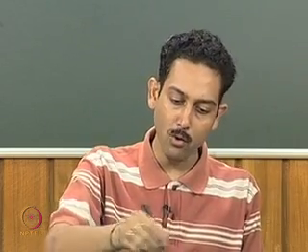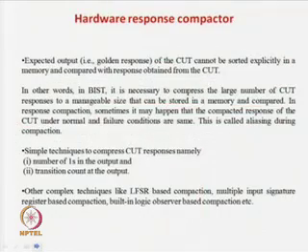So that is why we go for LFSRs. We can design the LFSR with the desired primitive polynomial, the desired characteristic polynomial, and if you want an exhaustive set, you have to go for a primitive polynomial; a list can be found in this paper. And if you do not require that, you can design another kind of characteristic polynomial, so that you may not have the exhaustive set of patterns, but you will have the required set of patterns. Again, if you want to select the sequence of patterns in such a way that your required test patterns arrive earlier, you can select the seed accordingly and your job is done. So that is how we design the pattern generator in BIST using LFSRs.